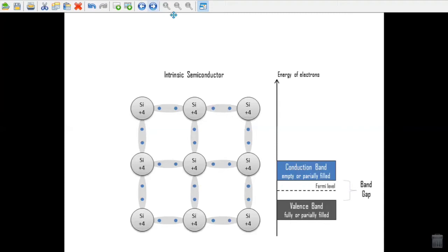Small changes in the base to emitter current, the input signal, cause either holes for PNP devices or free electrons for NPN to enter the base from the emitter. The attracting voltage of the collector causes the majority of these charges to cross into and be collected by the collector, resulting in amplification. Another kind of transistor that is very useful is the field effect transistor.